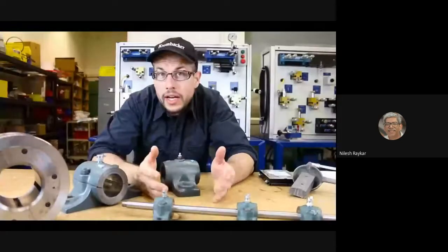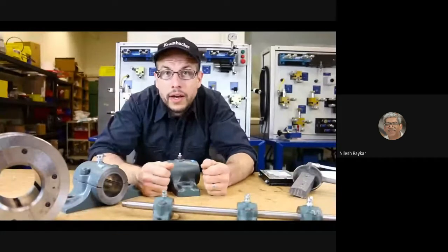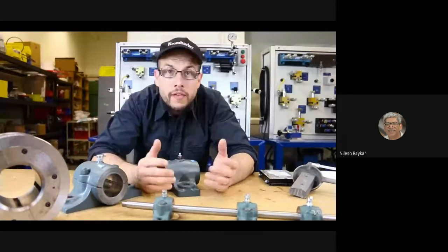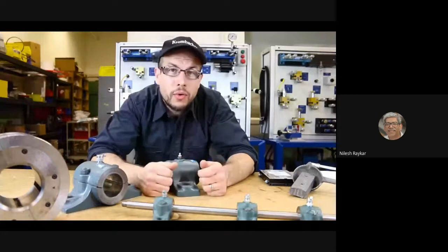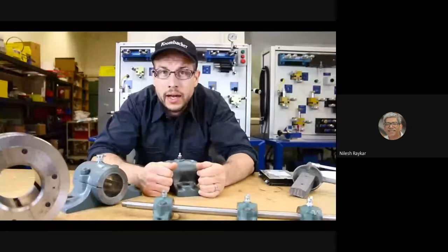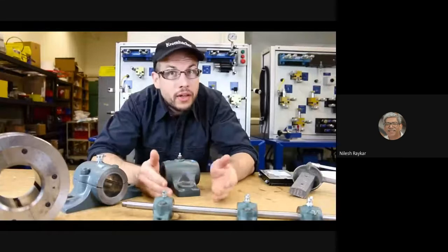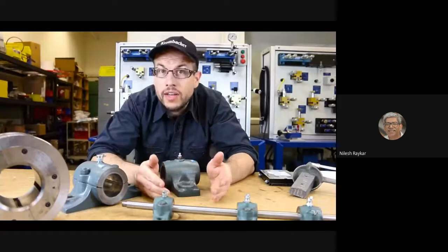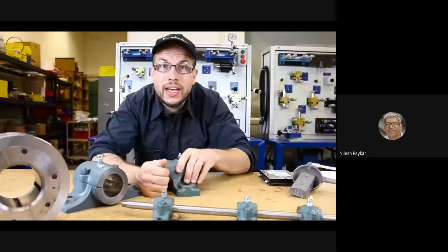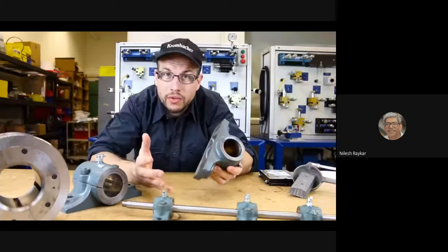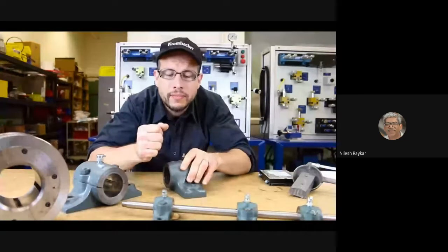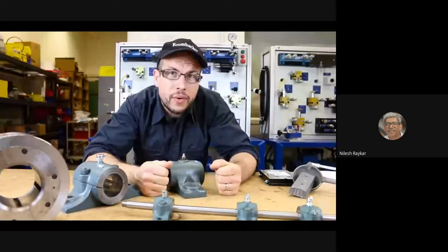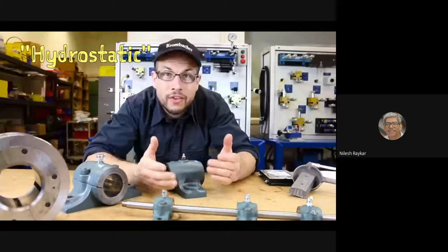There are a few variations on the plain hydrodynamic bearing which we've outlined here. For example, since the shaft needs to get up to speed for full film lubrication to form, the bearing is especially vulnerable to wear at both startup and shutdown. So the bearings in some very large, very heavy machines have auxiliary hydraulic pumps which actually pressurize the lubricant through oil slots in the bottom of the bearing. This helps to lift the journal off the sleeve. Sometimes these designs are referred to as hydrostatic rather than hydrodynamic.